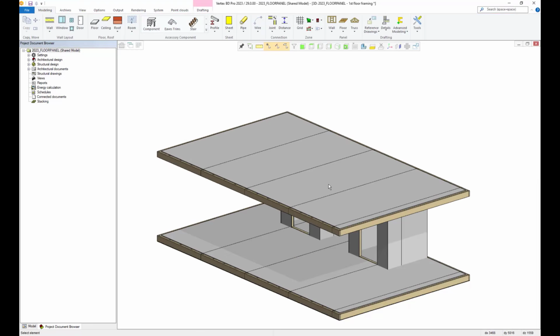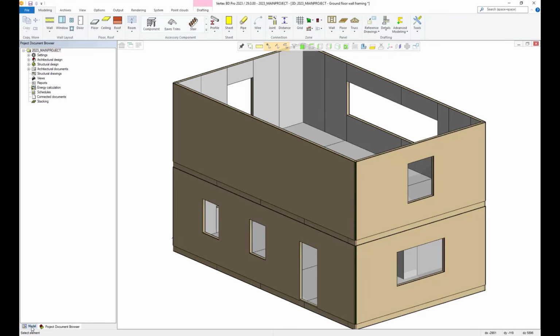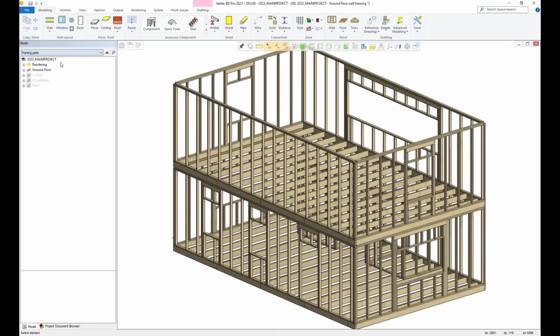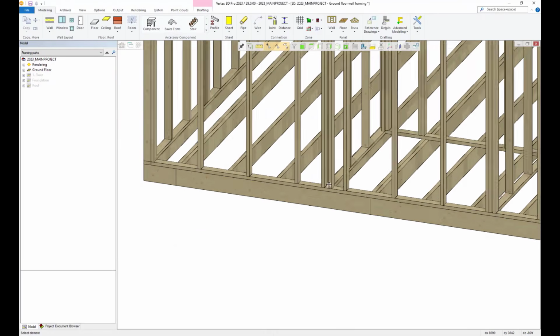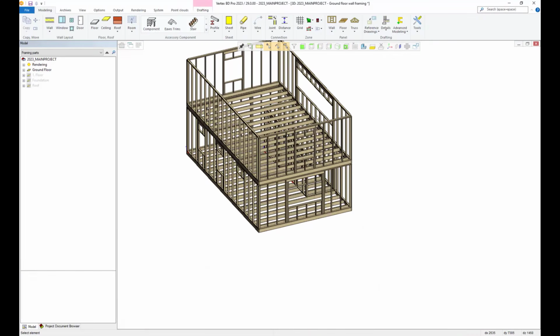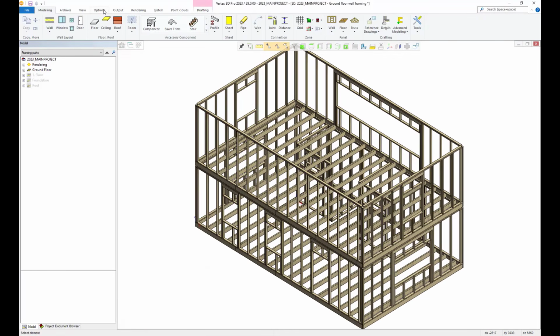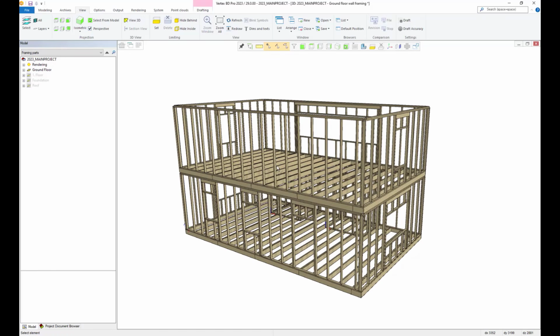Now with that complete, you can see we have our floor panels completed and ready here within our shared model. Now we save our changes and head back into our main project. As you can see, all our panels and parts we created are successfully implemented as per our shared model changes. You can also see our smart models, which were framed as they're required and include the necessary joints and backers. After this, you can now go on to creating your panel drawings from your main model. It is also possible to create these within the shared models if required. However, numbering is main project specific.